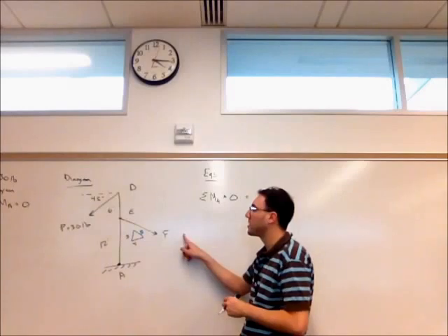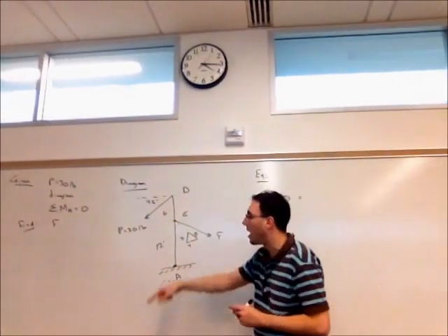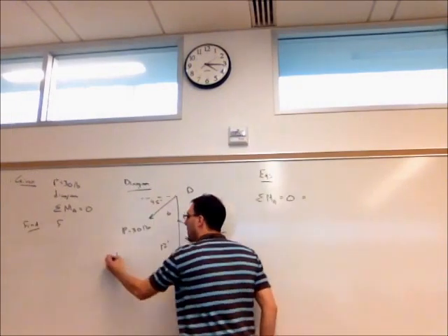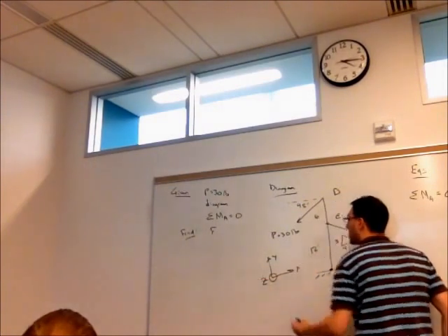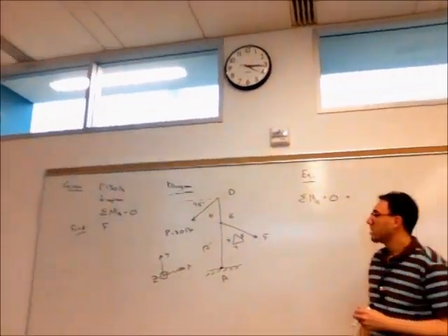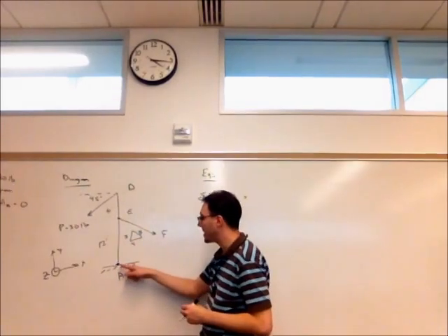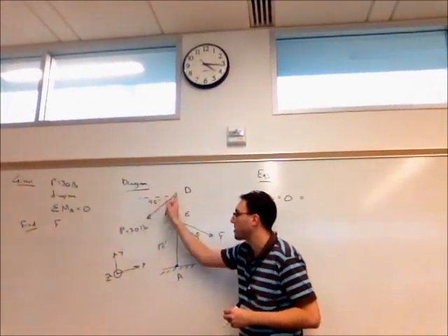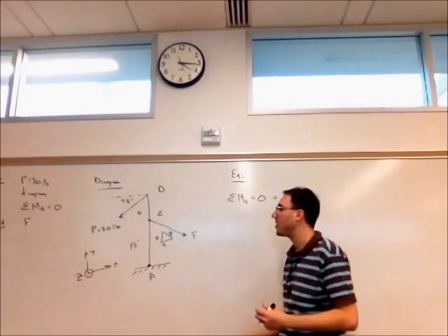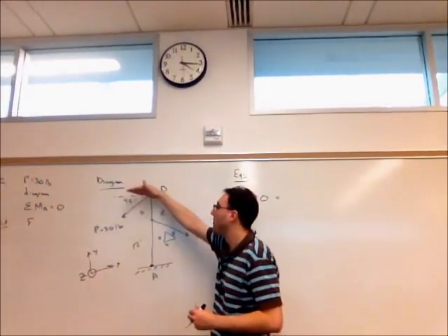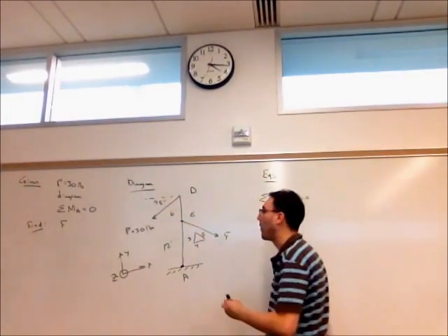So we're presented with a similar situation that we had in the last one. We have these forces going off in non-XY directions. We do want a coordinate system here. So we could find, since we want the moments around A, the distance between A and then the perpendicular to that line of action. But again, that's going to be tough to do. So an easier way to do it is, instead of finding that, breaking them down into horizontal, vertical components and analyzing it that way.